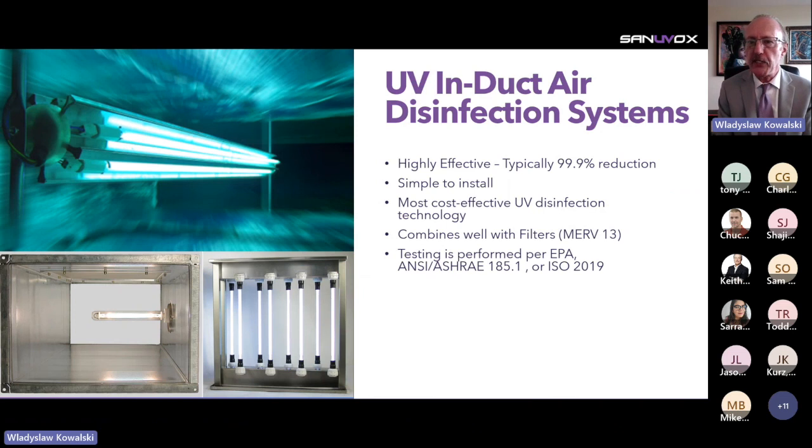In-duct air UV disinfection systems are highly effective. The EPA test performed in 2006 showed at least a 99.9% reduction. They're almost virtually 100% removal of most pathogens. They are simple to install, very cost effective compared with other technologies, and they combine very well with filters, particularly the MERV 13 filter recommended by ASHRAE.